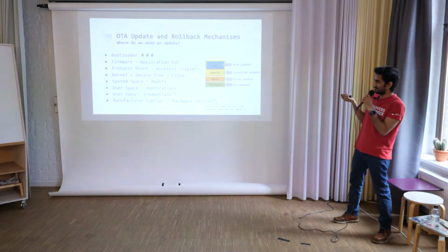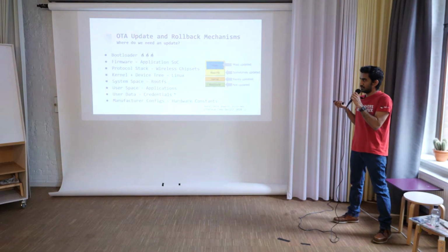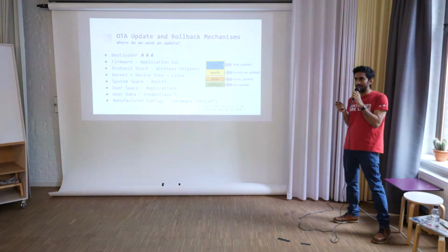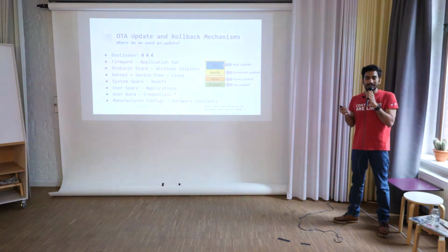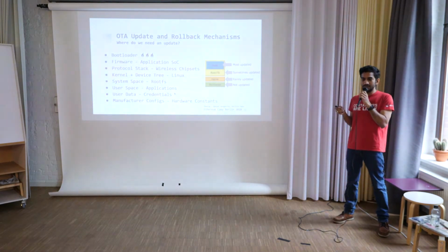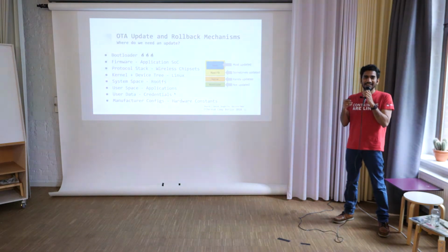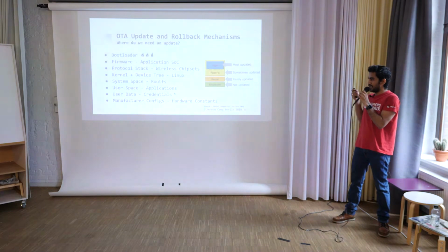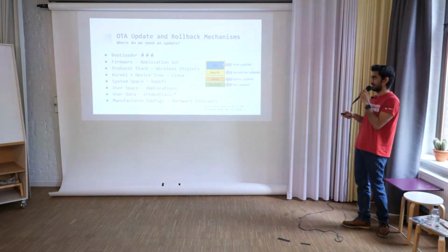We had a recent example, I can show you one of the products from NBT, where we were using a wireless M-Bus module from one of the big manufacturers. We said, okay, we're going to put your module in, and we need you to tell us how we can update. And they said, oh, you don't have to update because we have tested the firmware, there's no security fault. And then people believe that. But always, if you have a connected chipset, it has a firmware that has to be updated as well.